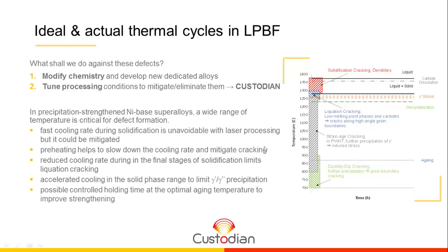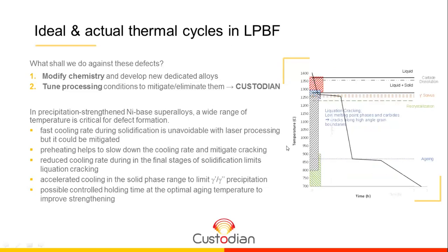Also, a reduced cooling rate during the very final stage of the solidification could help in mitigating the phenomenon of liquation cracking. And then, in the ideal world, if we want to optimize things, we can also speed up the cooling rate after that in the solid stage and hold the material at the proper aging condition. But it's ideal, of course.